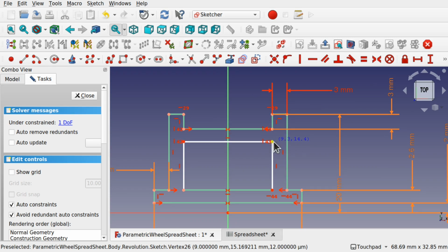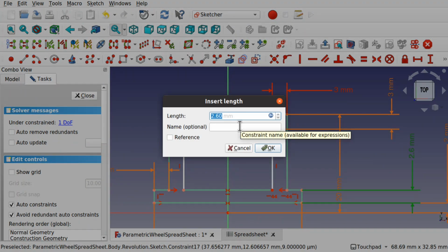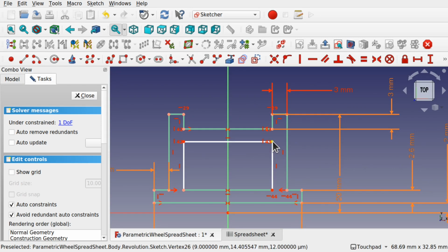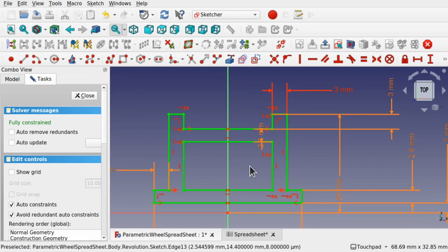So we need to set this height. Let's give this a name, 2.6mm, and name this to axle. It's the second diameter. I'm not sure what to call this. I'm just going to go sec dia and OK that, and we'll place a height in here, and that's going to be the constraints dot axle sec dia, and OK that. So that becomes a void.